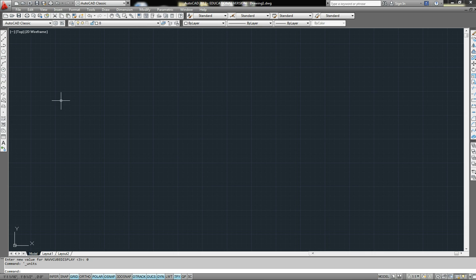First thing I want to discuss is how to use the line command. I introduced this a little bit in the last tutorial, but now I'd like to be a little more specific and talk about how to enter dimensions. So I'm going to activate the line command by clicking on it from the draw toolbar here. And notice here next to my dynamic tooltip, also in the command prompt here, it says specify the first point. This can be done a few ways. You can type in the coordinates for the first point, or even easier, or more commonly, you can click somewhere to start the line. In this case, it doesn't really matter where we start it. We can always move it later if we have to.